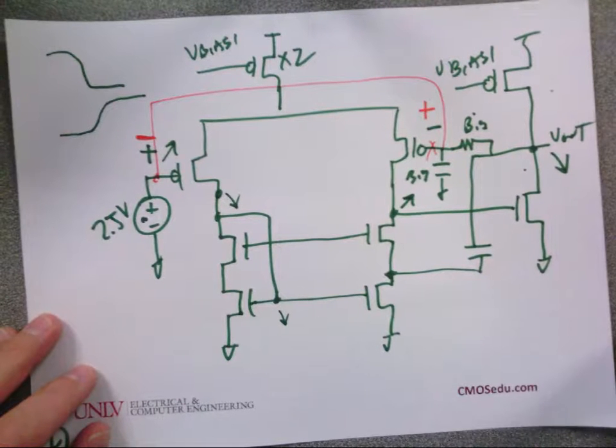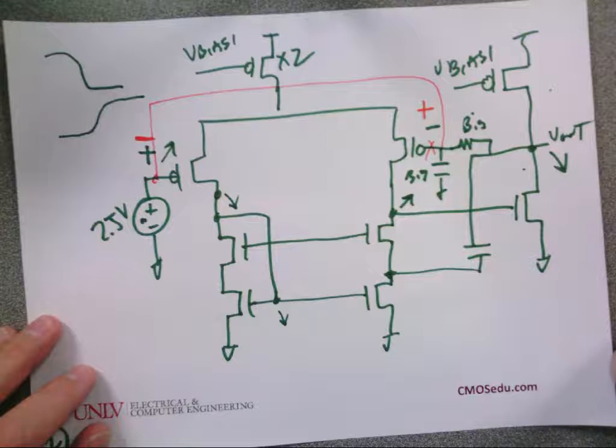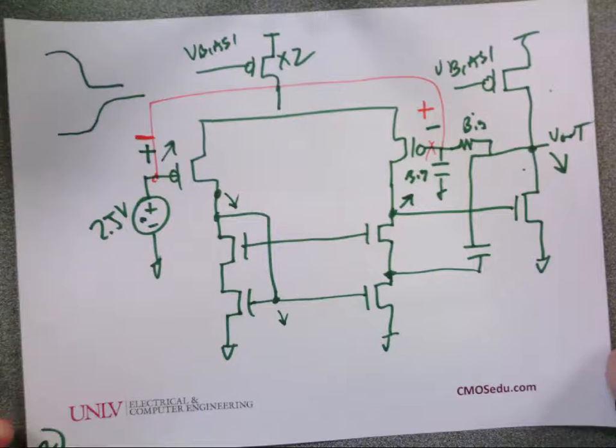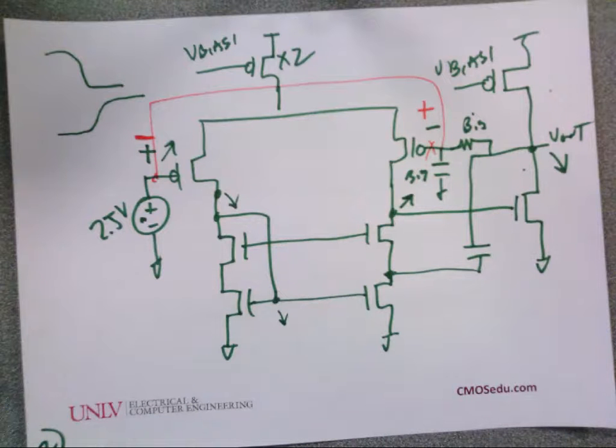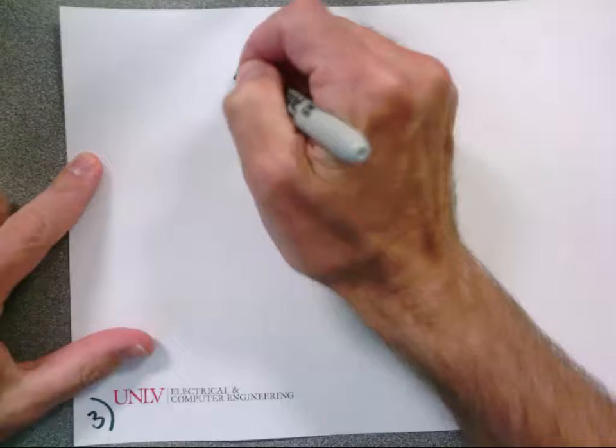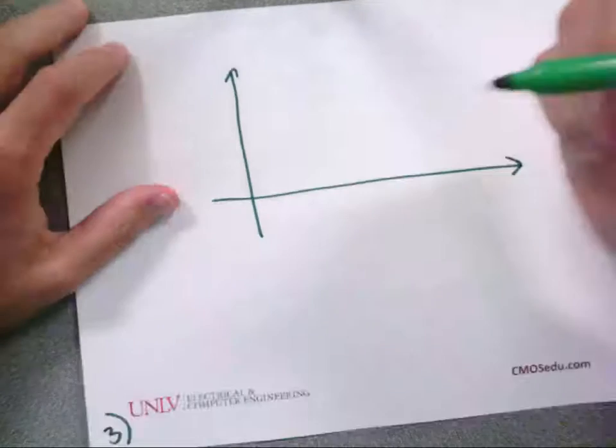So how do you reduce or increase the phase margin? I have to use the pole. No, you're talking really deep. I'm asking you, how do you increase the phase margin? Just tell me real simple. Oh, my phase margin's only 60 degrees. What do I do? I think increase CC. Yeah, increase CC, or I can increase the transconductance, and it'll push the pole out if I want to do that. If I reduce the transconductance. But let's ask that just to make sure everybody follows. Let's say that I have the following.